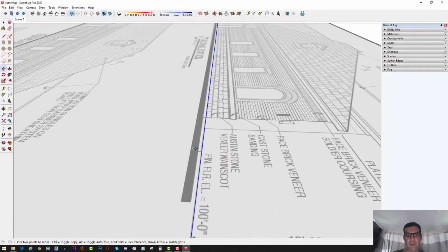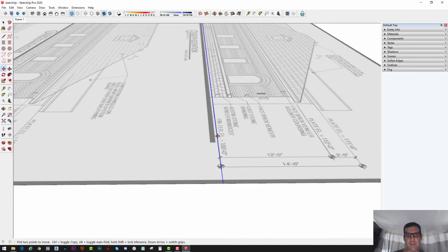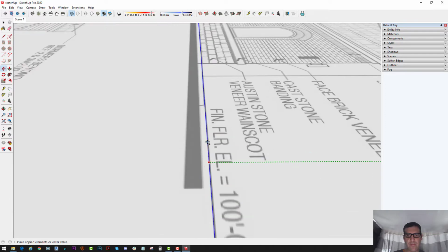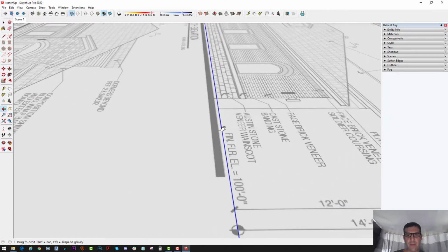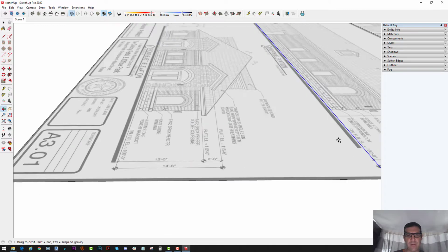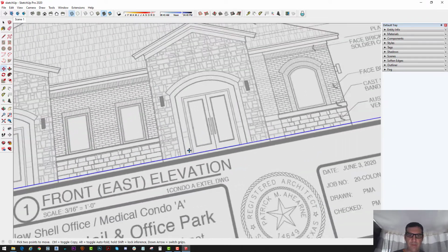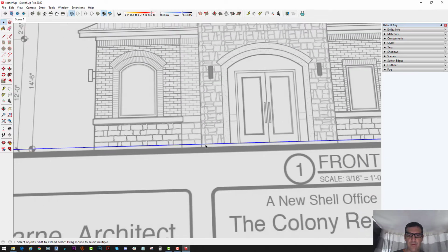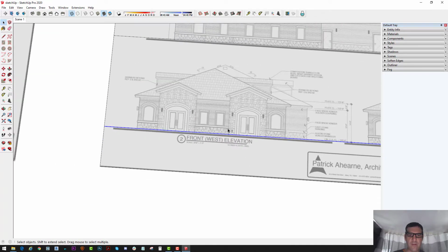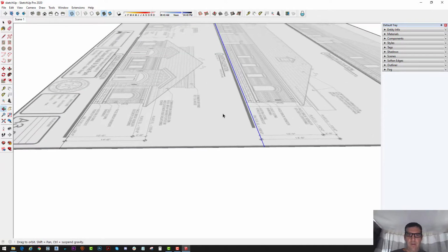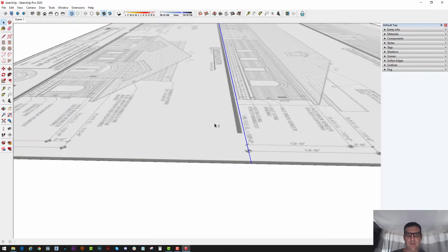There's a sidewalk there, but I'm just going to do it to the bottom of the building. And then click on that line again, hold down Control to copy the line, and make another one over here in the middle of that line, right at the bottom of the building. Then do that down here with these ones, so it's at the bottom of the door. That's the floor. That's like where the finished floor, they call it, in the contracting building world.